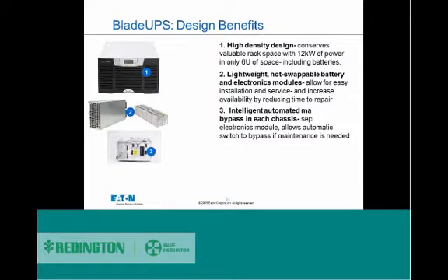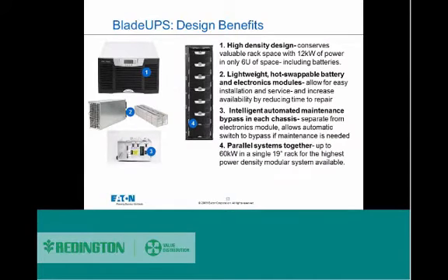Finally, we'll go to the blade UPSs. Again, these are all with power factor 1, so you can see that each of them is 12 kilowatts of power. They use about 6 U of rack space.